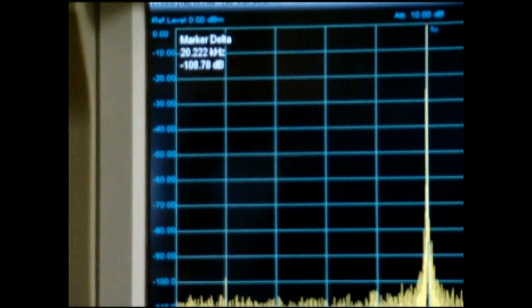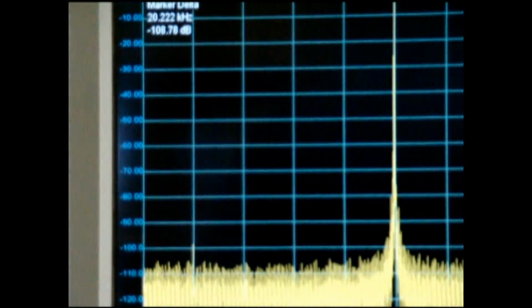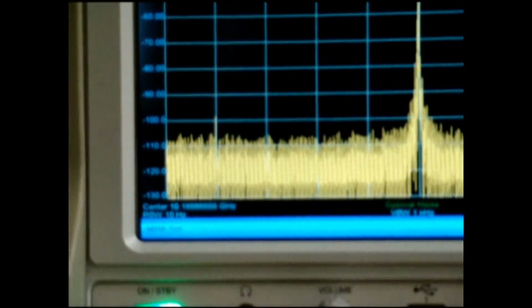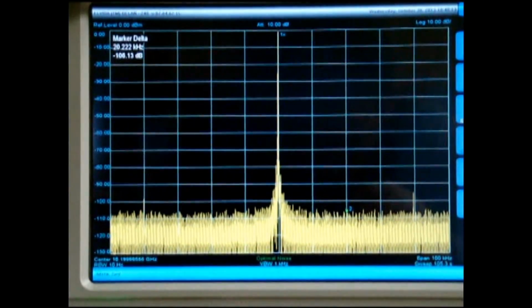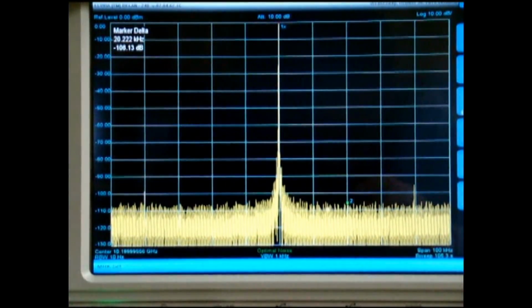It should be mentioned here that the results of both units are quite respectable. The difference, shown here, emphasizes the importance of the analyzer close-in phase noise for this type of high dynamic range single-tone measurements.